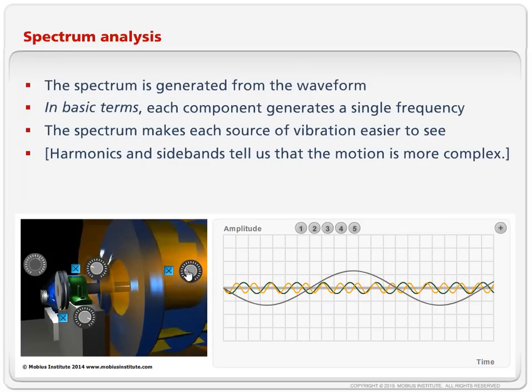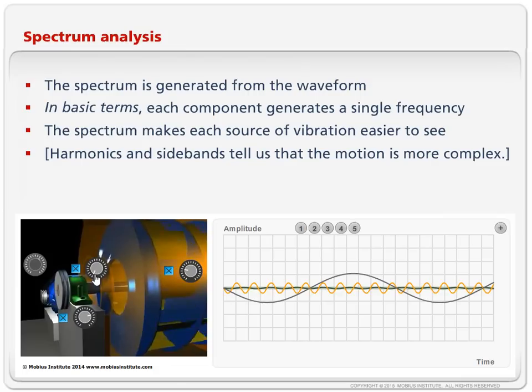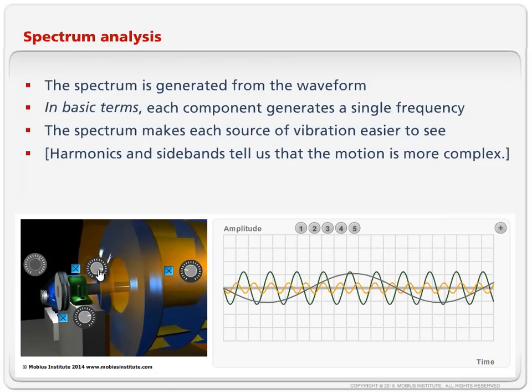Now, from everything that I've described, hey, you're a budding vibration analyst now. If you could see what I'm seeing there, and you see that the little grey waveform is low in amplitude, you'd be saying, oh good, the machine's nicely balanced. Oops, it's not as balanced as well. Oops, the bearings are in good condition, the bearings are getting worse and worse. So you get the idea.